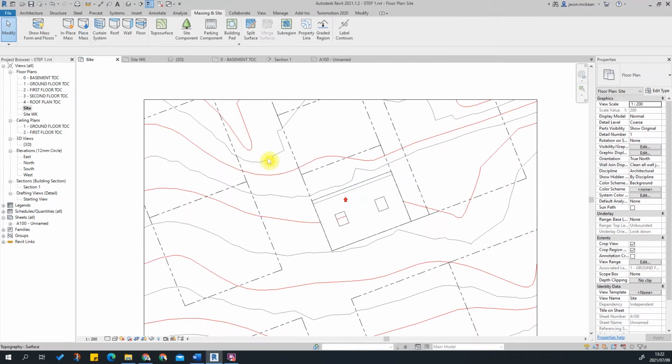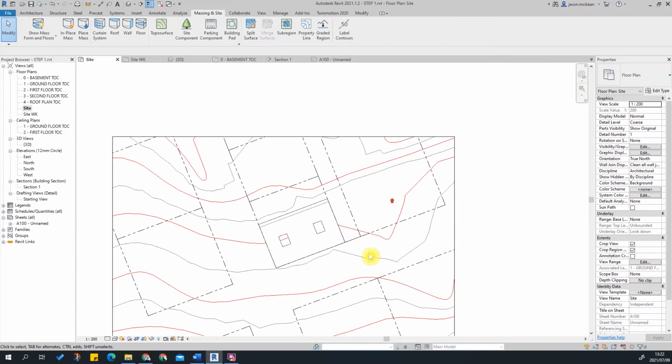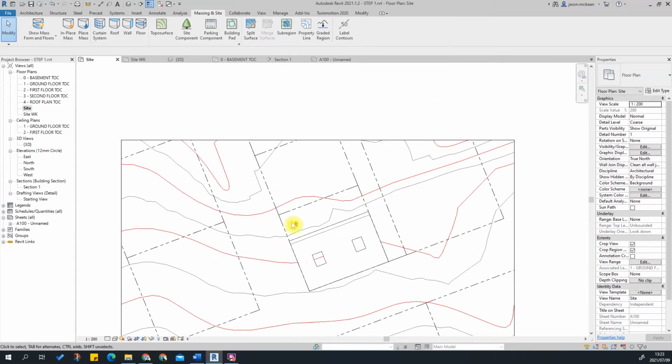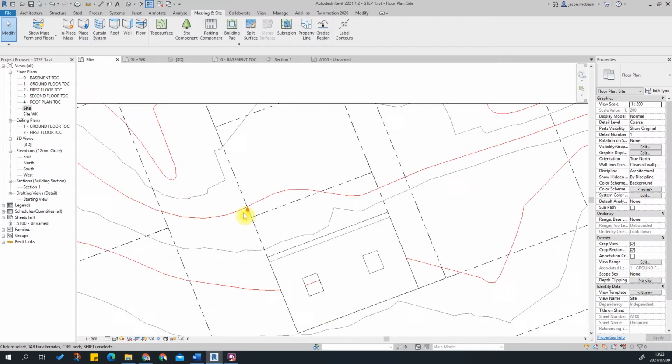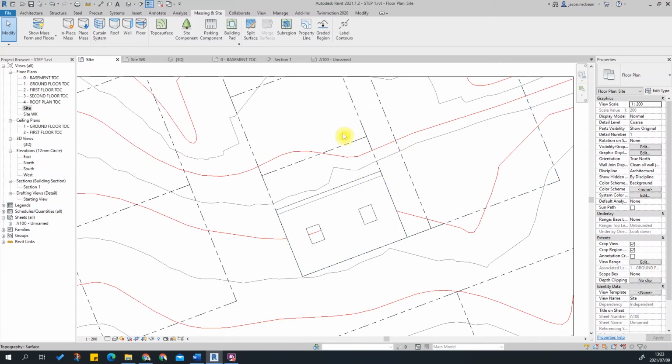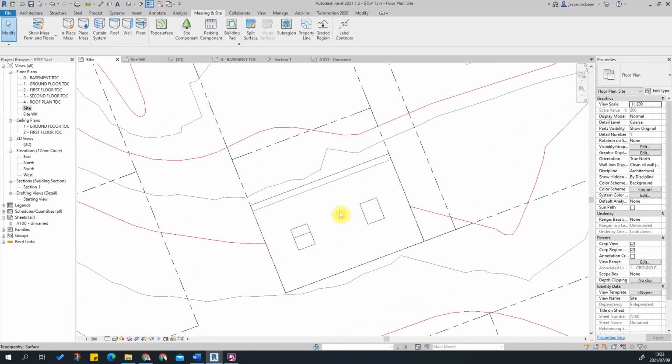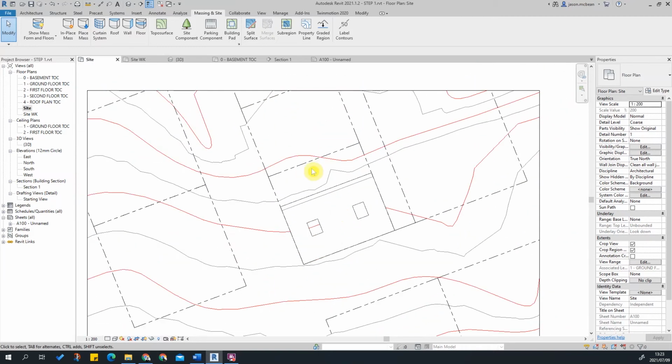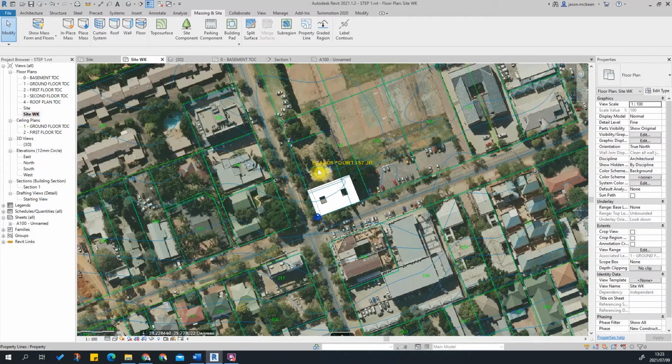So we're going to start building the road network, the adjacent parking, and in addition, I know this is an annotation category, but I'm going to establish some grid lines on our site so that we can work a lot more accurately going forward. So the first thing I will tackle will be introducing some grid lines. So this is what I'm going to do in my working view. So a lot of this will happen in my working view.